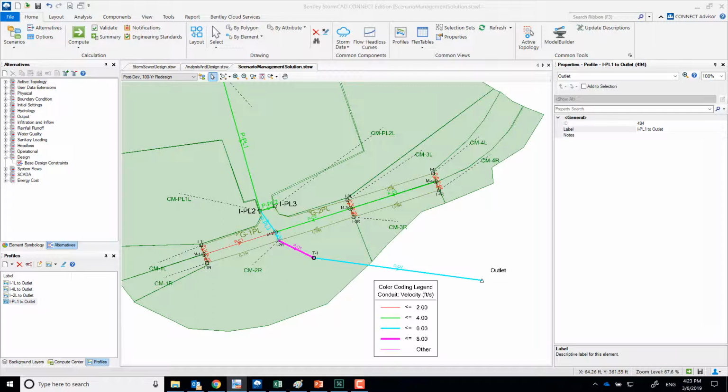What is the typical range of values for the rational C coefficient? So theoretically it's 0 to 1 because it's really, kind of like what percentage of the rainfall becomes runoff. So it's either all or nothing, all being 100% or 1, nothing being 0. But in reality, there's always some rainfall loss to ponding, or it evaporates before it gets to its end. So between like 90% and 1 or 10%, so 0.1 and 0.9.